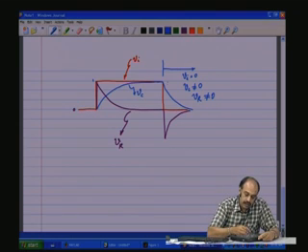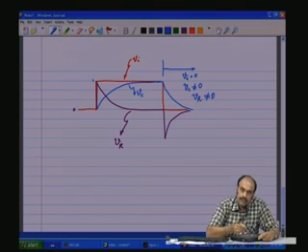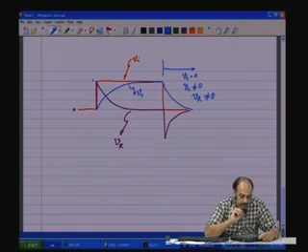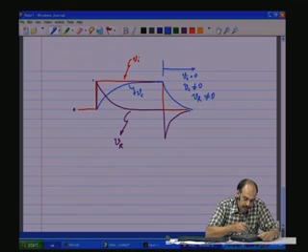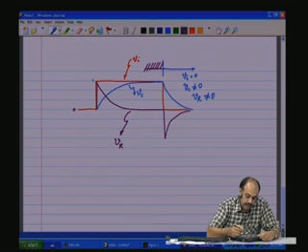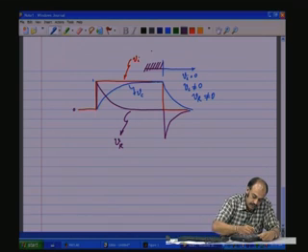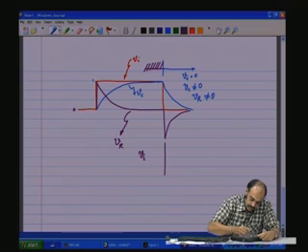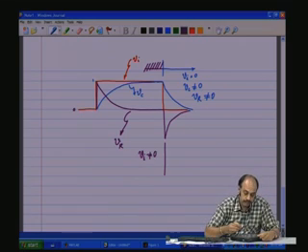How fast or how slow it decays gives you the position of the pole in the S plane. So, that is the major concept that you should understand. Now, just before that, when the input is existing, that is during this portion of the time axis, here Vi is non-zero, that is Vi is not equal to 0.